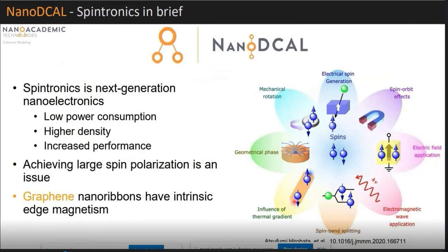or devices. It can also work on spintronics, spin up, spin down calculations, movement of spins, rotations of spin atoms, or any polarizations, whatever you want to simulate, or whatever intrinsic magnetic movements, including the photocurrent effect. You can also do the study by defining some polarization, elliptical, vertical, horizontal polarizations, electromagnetic waves you can apply on your device regions, and you can study the spin effect on the device characteristics.